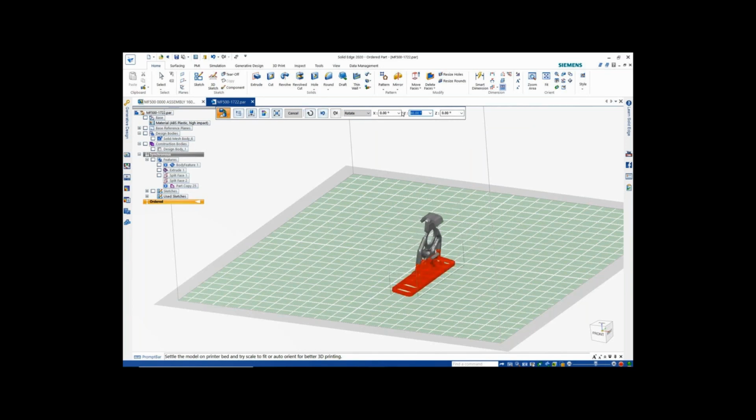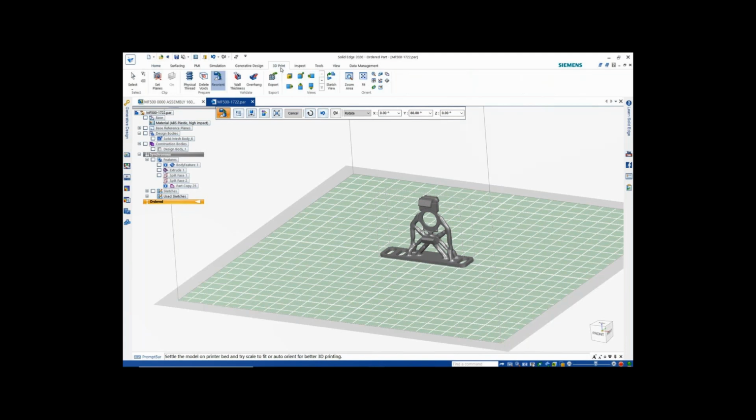I'm just going to bang in something close to 90 to illustrate that there's a great feature to reorient by using the settling process. It finds the flat area, and has an optimized rotating capability that will find the best orientation. Maybe if you were going to print 40 of these at once, this would be very useful to get them all nested in there just so.